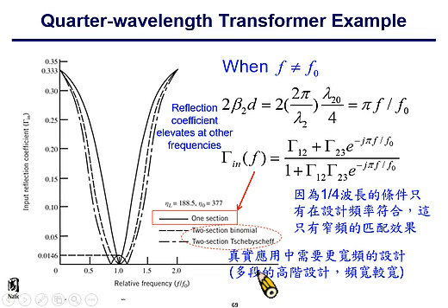And the other line is the so-called Chebyshev design. As you can recall from your undergraduate circuit design courses, the Chebyshev design will touch zero reflection several times according to the order of the Chebyshev design. In this case, you have just a two-section Chebyshev design, so you touch zero reflection twice.